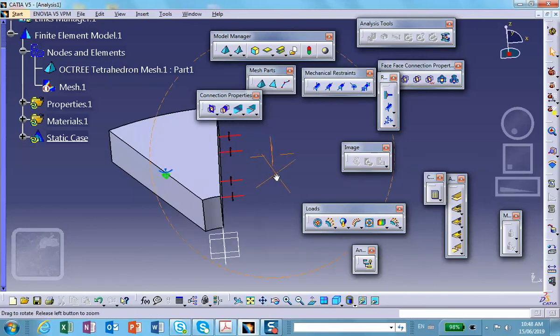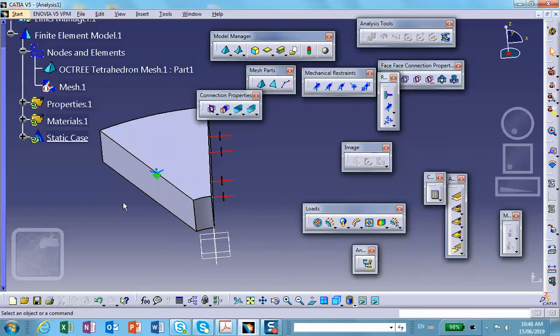First of all, surface slider means that there is no displacement perpendicular to this plane. However, the problem is that this plane that you see here is at a 30-degree angle. Being at a 30-degree angle, it's neither aligned with X, nor Y, nor Z planes. So what we're going to do is create a local coordinate system. So how do we do that?